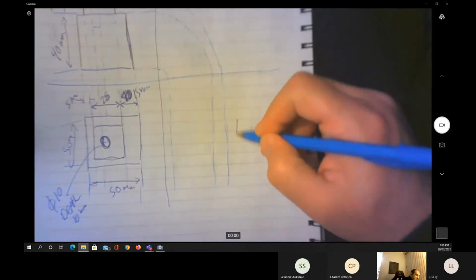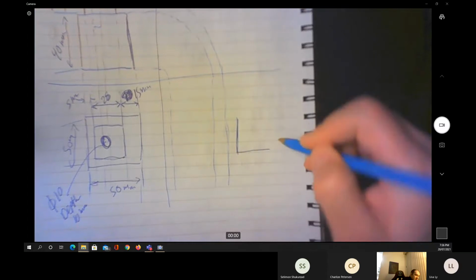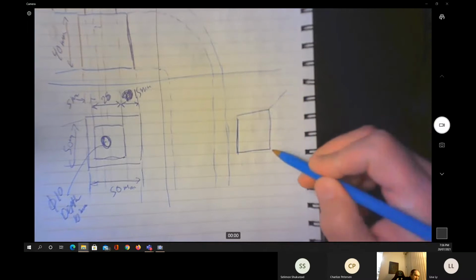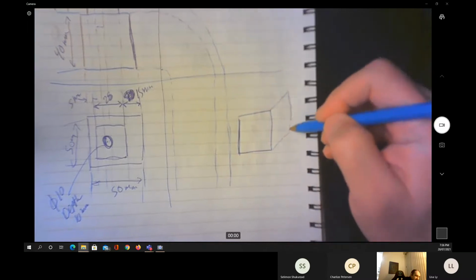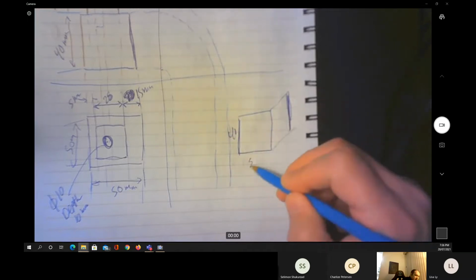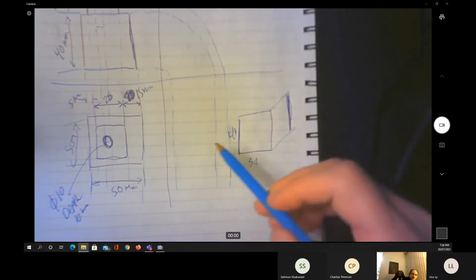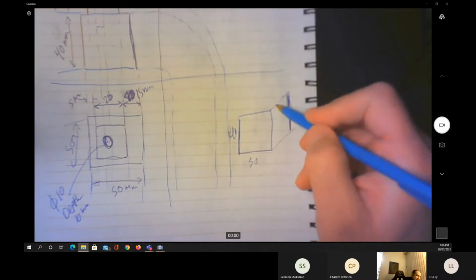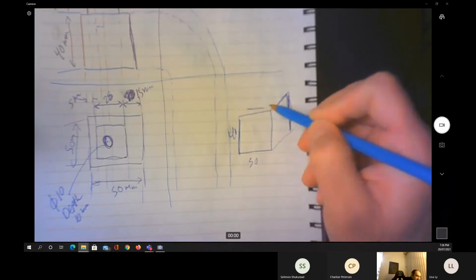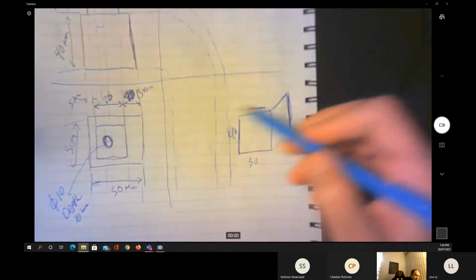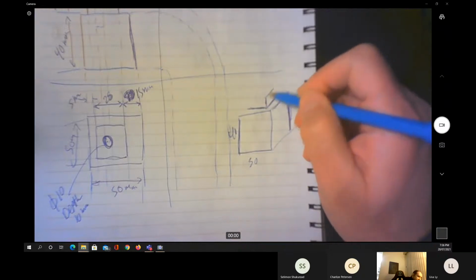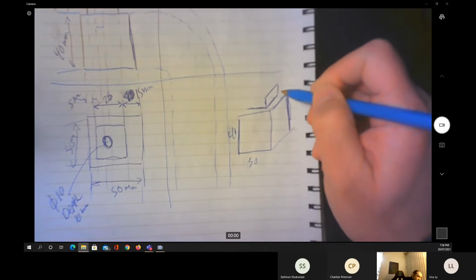The 3D part is going to look like the following. We always make the front face. Then we are going to sketch something by 60-degree angle. Okay. Obviously, what we have here is going to be 40 for the height and 50 for the side, because you know that the height is quite lower. Okay, and I'm going to make the other block at the top here with the dimension given here. Okay, and this one is at the height of 10 millimeters.